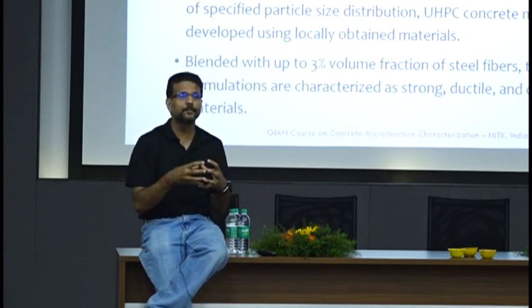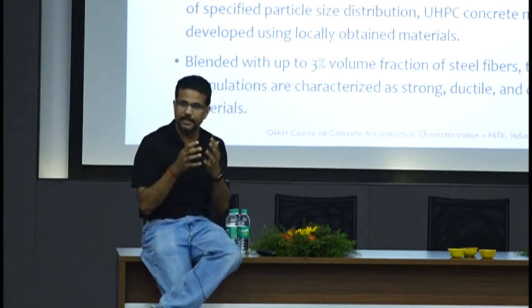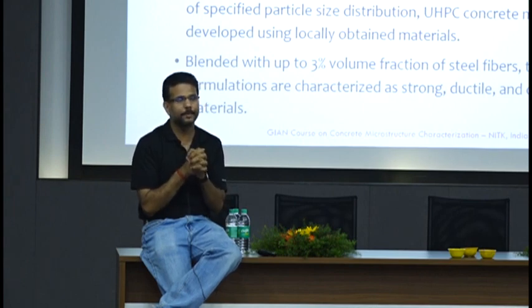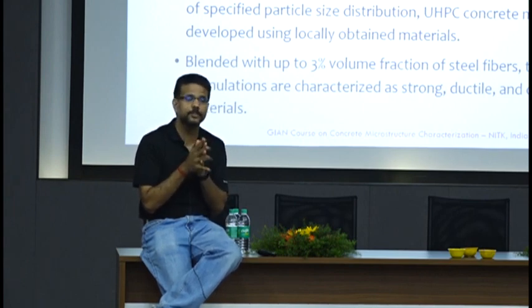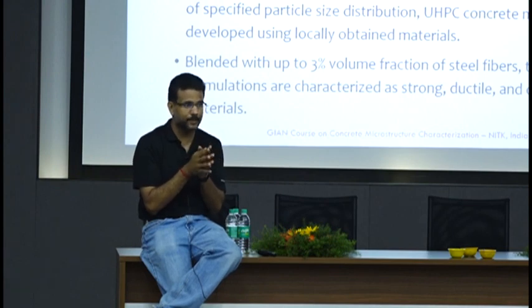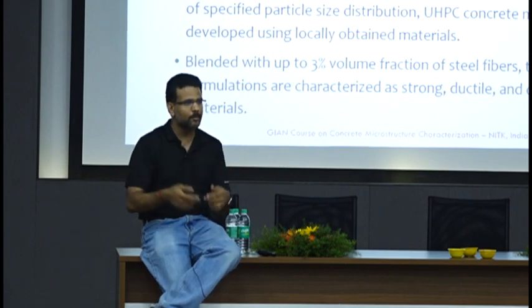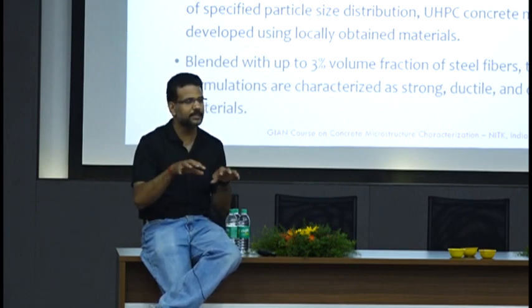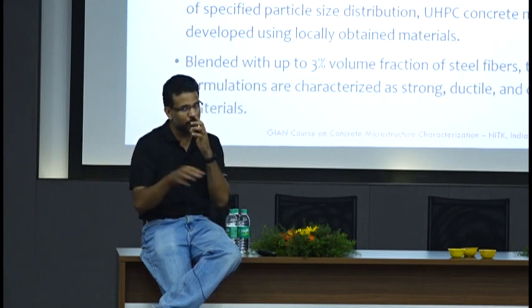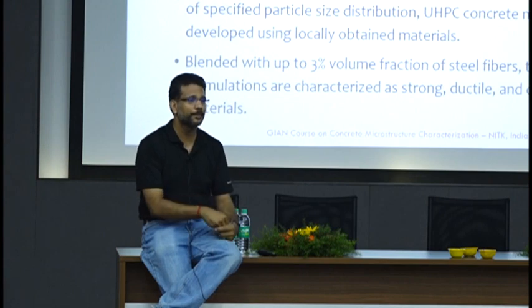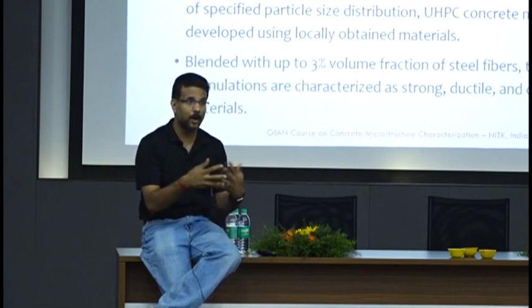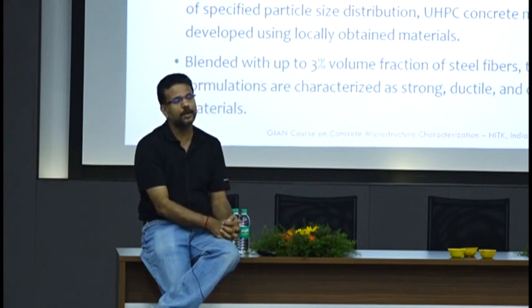Because of the effect of superplasticizers, even the latest polycarboxylate based superplasticizers, which are supposed to be very quick in dispersing, when you have a low amount of water, you basically have to stretch them out by mixing more and more and getting water away from the particles. You get the steric hindrance away, you get the agglomerations away, so you have to get all of that, and that's why it takes long. But good mixing is key. And that's where a lot of energy is spent, and that's where the cost is increased.